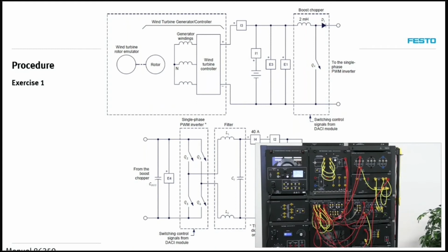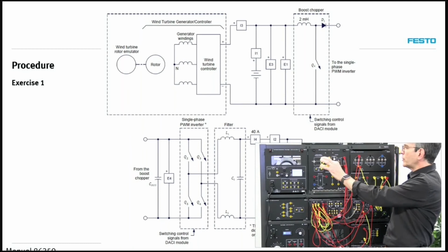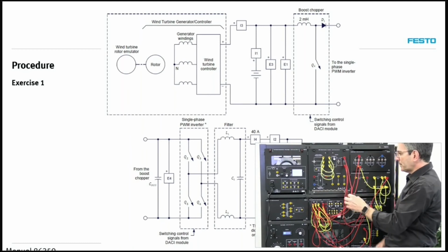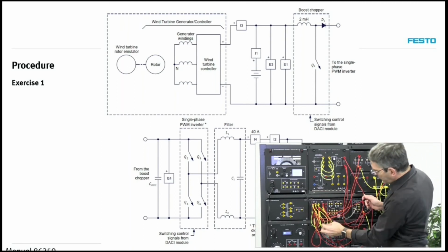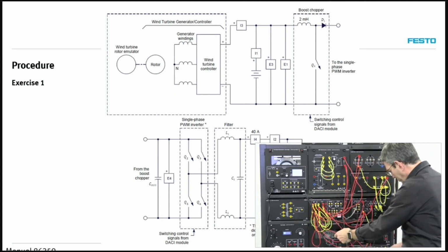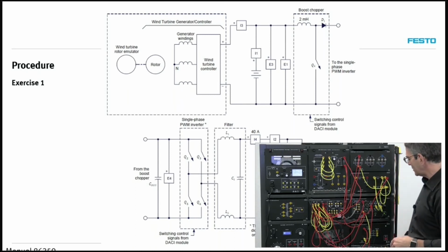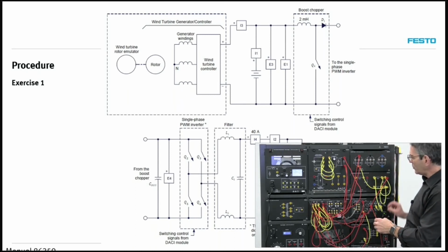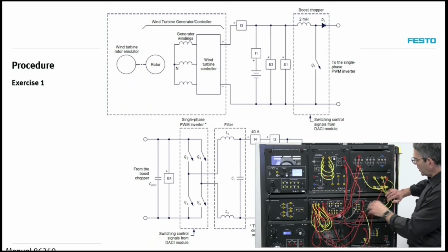Okay, so I've already shown you the first part where we connect the output of the generator. Then the battery signal goes into an ammeter down here, and from the ammeter output, it goes to the inductor here, for our boost chopper. This is the inductor required for the boost chopper. And then we get to our IGBT module. This module here is really important.